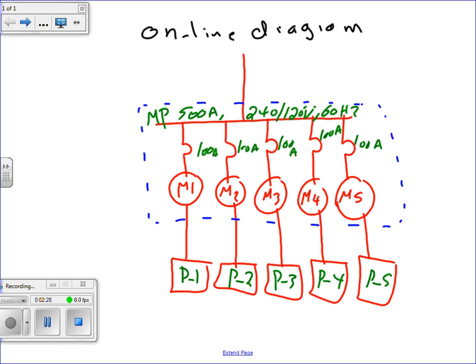Does that make sense? The flow of logic in it, Chris, especially you, my friend, you're a computer engineer. You bring the power to the meter center. From the meter center, you distribute the power to the panels. And Nick, we always stop at the panels. When we go to the commercial project, we will talk more about the difference between a riser and a one-line diagram. For the time being, think of a riser or a one-line diagram from a power point of view. It's bringing the power to the building and distributing the power in the building. And Rob, we stop right at the panel. We don't go down to the branch circuits. Right at the panel. Cool?